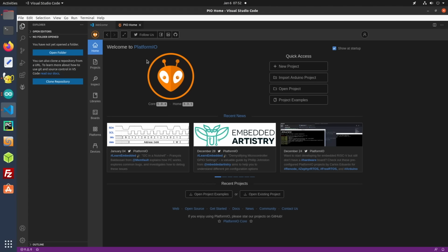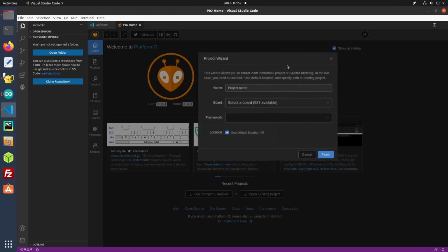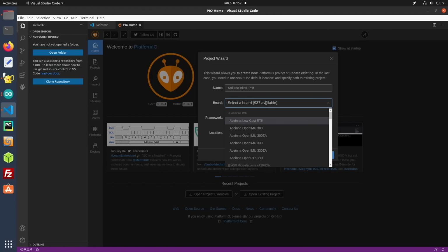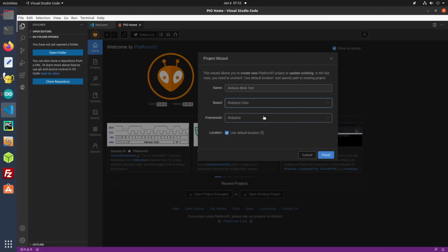Let's go back to the home page right now, and let's start a new project. And we're going to give our project a name. I called it Arduino Blink Test, so you can sort of guess what I'm going to do here. Now we can select the board that we've got attached. Now there's 937 available, and we could scroll through the list, but it's much easier just to start typing. And then Arduino Uno has been found over here. The framework is the Arduino framework. And we'll hit finish. Now this can take a few moments when you're first starting PlatformIO because it needs to load a number of files the first time.